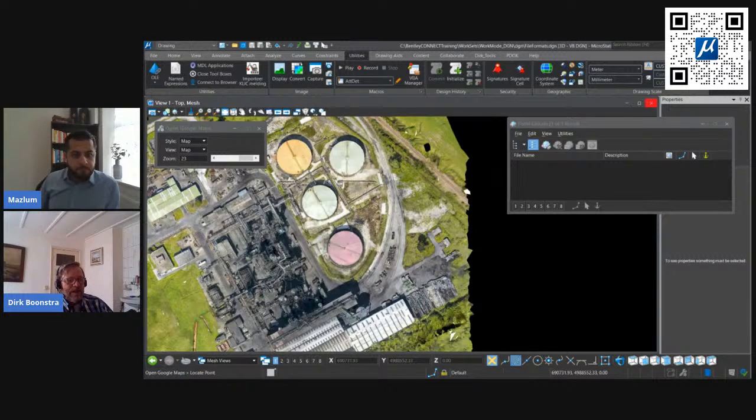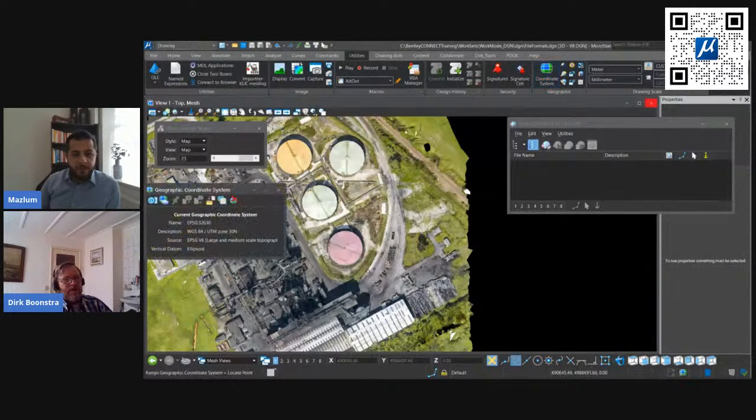An architect sometimes uses an X and Y coordinate system based on the street grid lines, but not related to any national or federal grid system. And that is very clumsy, because then you really don't know where the building is going to be. And so it's good to use the coordinate system that is used for the grid. MicroStation has the capabilities then. If you use a rectangular projected coordinate system with X and Y, because that's most of the time what you use, then if needed, you can translate to long lat, to geographical coordinate systems.